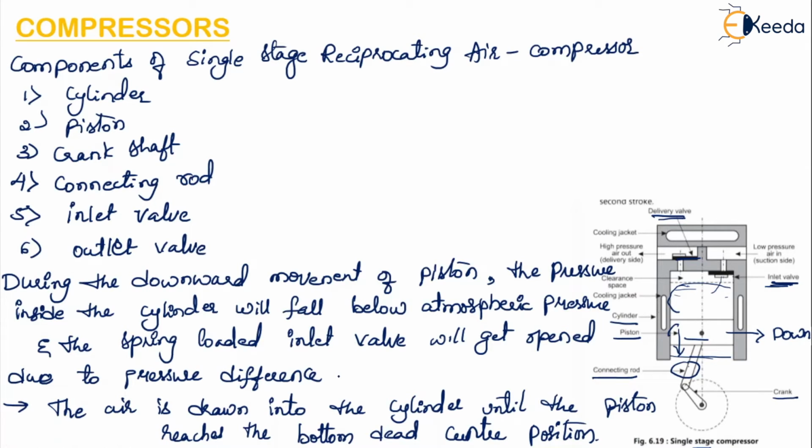So what happens when the piston moves down? There will be a fall of pressure inside the cylinder, and that is why the inlet valve will get opened and the air will start flowing inside the cylinder.